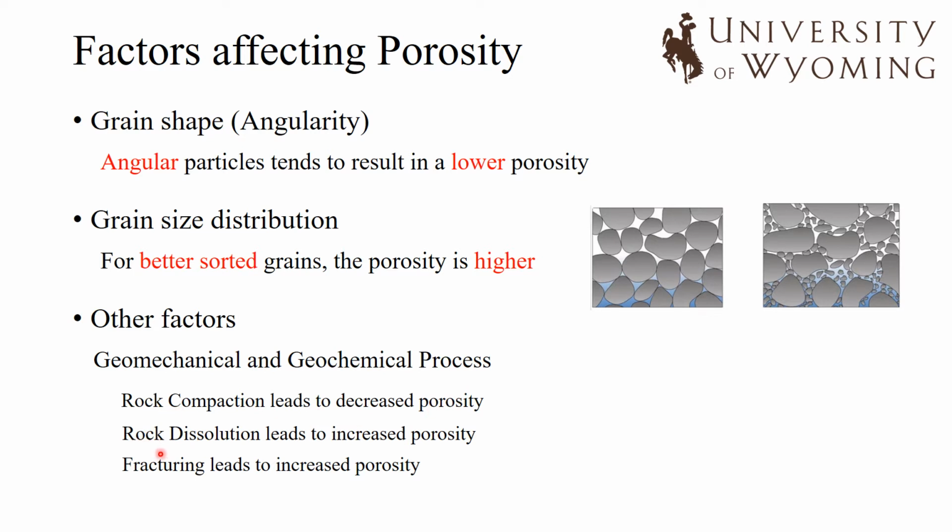Another factor is rock dissolution, because sometimes fluids move through the porous media, and those fluids can etch and eat the rock, and when they do that, they also tend to increase the porosity of that rock. The last thing is fracturing, which is also due to the stresses acting upon the formation. These stresses could cause fracturing and fissures to occur, which also increase the porosity. We call this secondary porosity, and that rock is described as having dual porosity.